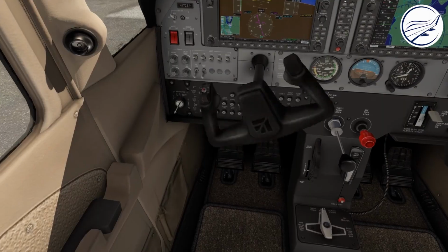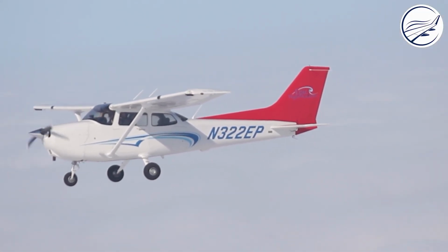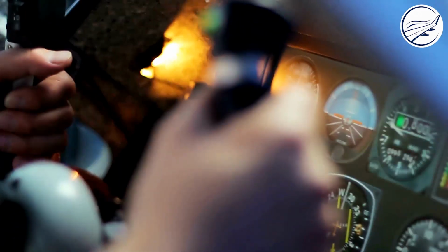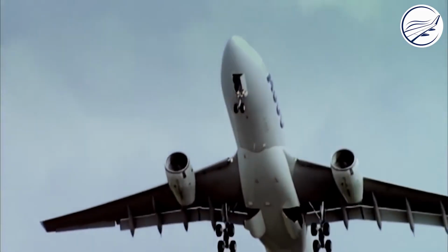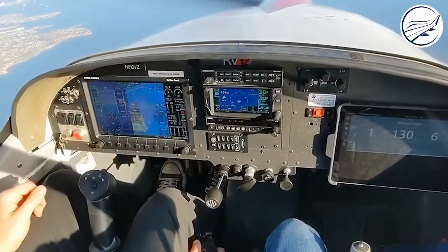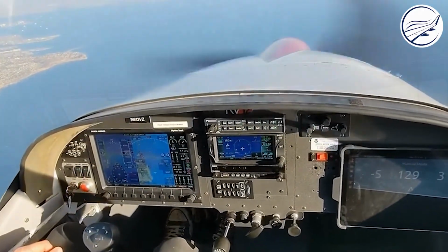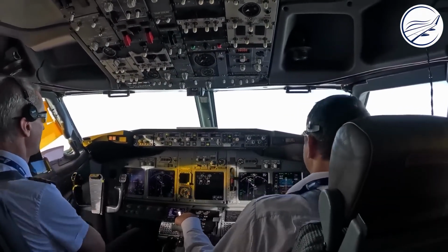To understand the true genius of modern aircraft control, we have to look closer at fly-by-wire, FBW. In older legacy aircraft, if a pilot panicked and pulled the controls back too hard, the plane would tilt its nose up until the wings lost lift and stalled, potentially falling out of the sky. But in a fly-by-wire system, pioneered largely by Airbus and now standard on almost all new Boeing and Embraer jets, the flight computer acts as a high-speed filter between the pilot's hand and the aircraft's wings.